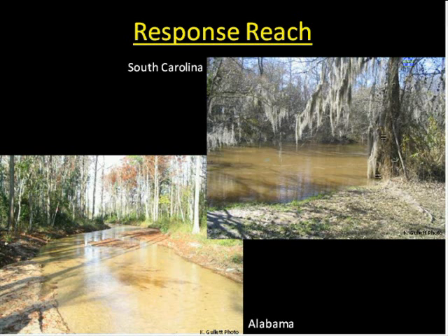Substrates are generally small and in large supply, and large woody material loads can be substantial. Response reaches are where the majority of our customers live and work, and where we are most often asked to help. These reaches are sensitive to landscape and hydrologic changes within a watershed, and channel adjustments can be significant and fast. Consequently, crossings in response reaches must be designed with consideration for a wide range of channel changes with the potential to extend for significant distances up and downstream.